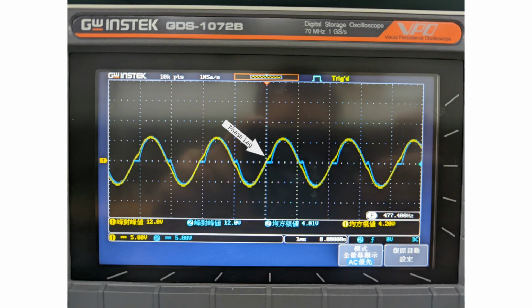Now onto the experiment. We start with the low-frequency input. On the oscilloscope photo, the output waveform matches the input almost perfectly, no amplitude attenuation and minimal phase shift. This shows low frequencies pass through easily.